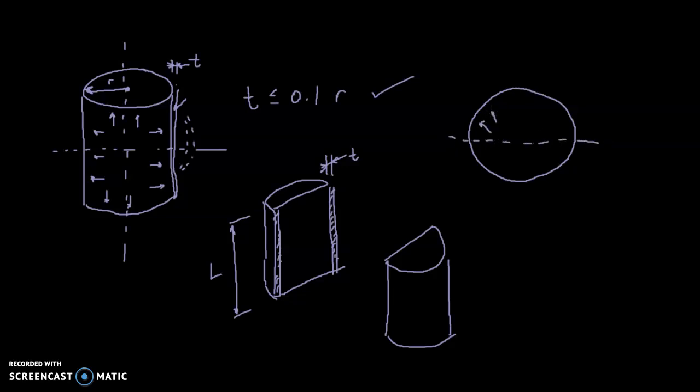That pressure is acting out in all directions. Okay, so we have a bunch of little force vectors acting out. There'd be one right here, theoretically, that's perfectly vertical, and maybe one down here at the bottom that's perfectly horizontal. And all the others in between are somewhat diagonal, so they have a little bit of a vertical component and a little bit of a horizontal component.